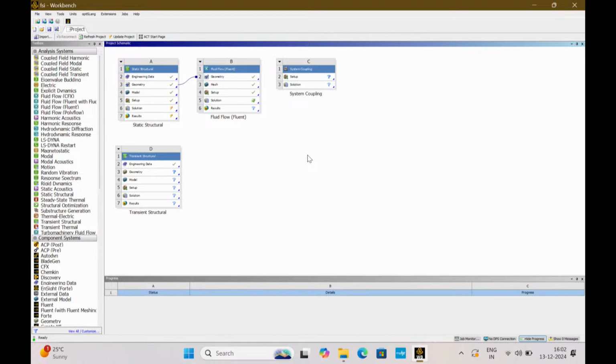Here we have not changed anything about that autosave that we have done. No, autosave is required for pulsatile flow simulation. Here for steady state, why is it required? For steady state, it is not.